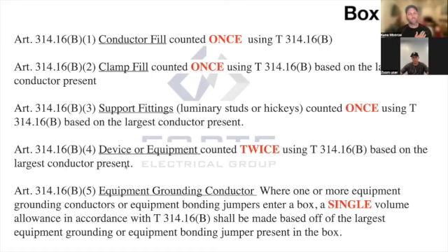I don't think they add 2 different sizes on you guys on your Journeyman's test, so just be aware of that. Always use the higher. Always use the biggest size one. Always. And it's right there. You may want to highlight that in your code book, largest conductor present, just to give you a little reminder on that. But that's how you do box fill.